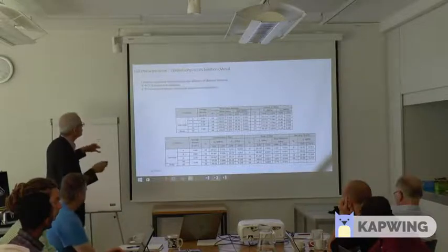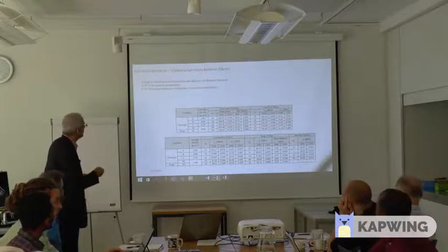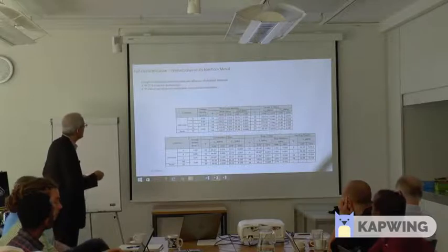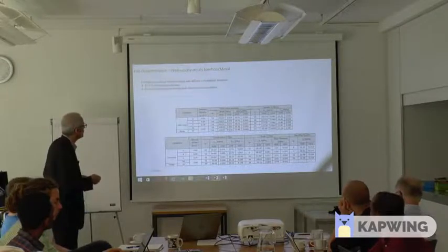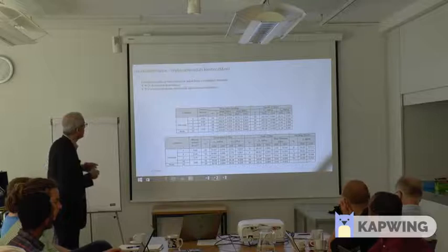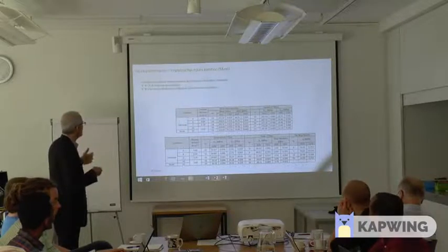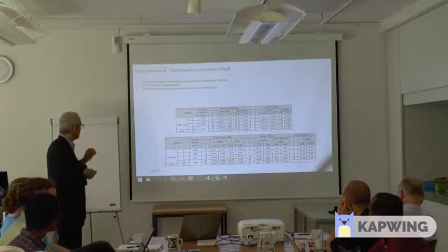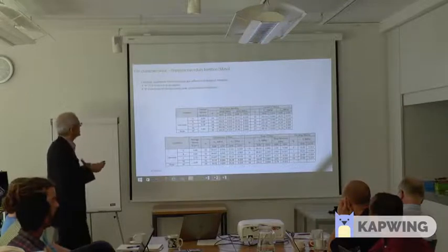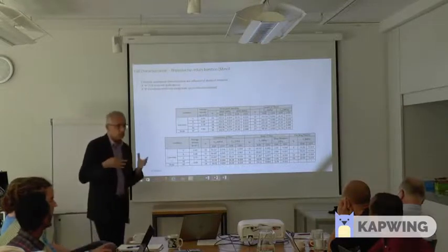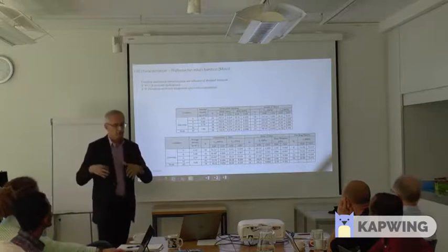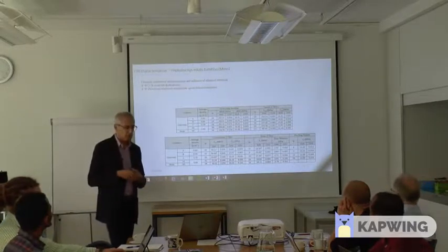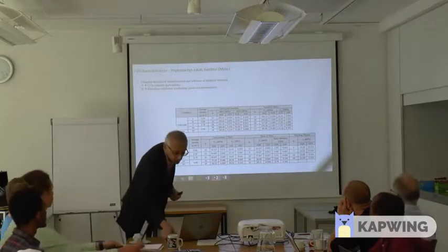There is not much difference, for example, in a bending test, in modulus of rupture or modulus of elasticity. There is not much change in the behavior of the material depending on whether it's A, B, or C, always working in this case in the internode part of the material. So this is a kind of study that could give us more support for standardization or even for designing using that material.